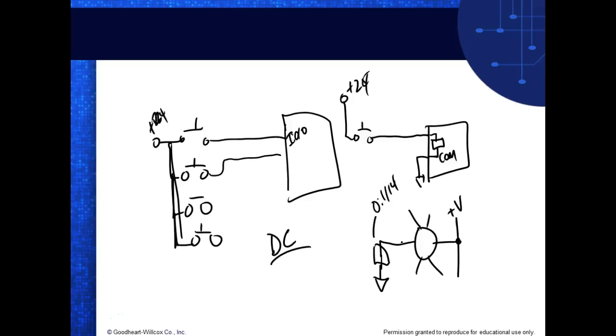So if you look at the MicroLogic, the SLC 500, SLC 504s down there, you see the input module says, anybody on it says what? Sinking. So that means if I was to wire up those inputs, I would use a positive common, right?